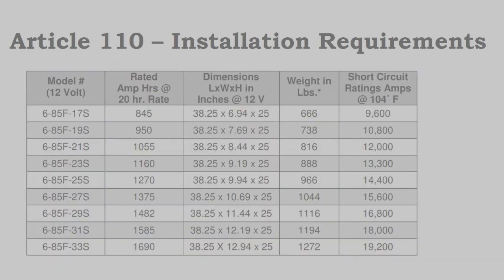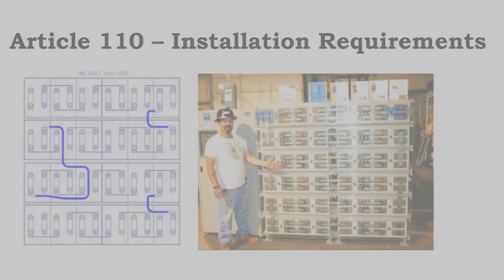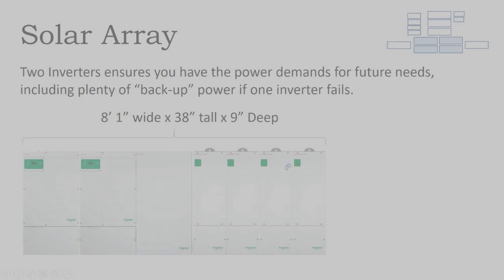And also just the practical element of how are you going to get the batteries to the room if you're using heavyweight batteries. Those are issues we talk about more in the battery management class, on why you might choose a 2-volt battery to have 48 batteries in your battery bank instead of a 12-volt battery and have 8 batteries in your battery bank. It's all about, can you move the batteries around, or do you have to carry them in? If you have to carry them in, you might go with the smaller, more lightweight battery and have dozens of them.